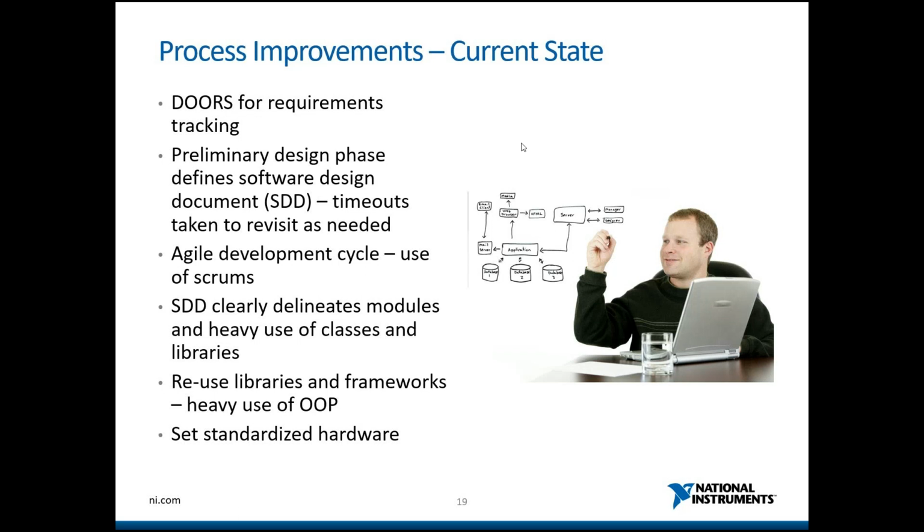How to resolve reuse toolkits for different versions of LabVIEW. There are a lot of different thoughts on that. What we started doing was using VIPM. You find the oldest version that's common to all the projects you want to use it in, write it in that if you can, and then make it a VIPM package. When they install the VIPM package, it will automatically upgrade to the correct version.